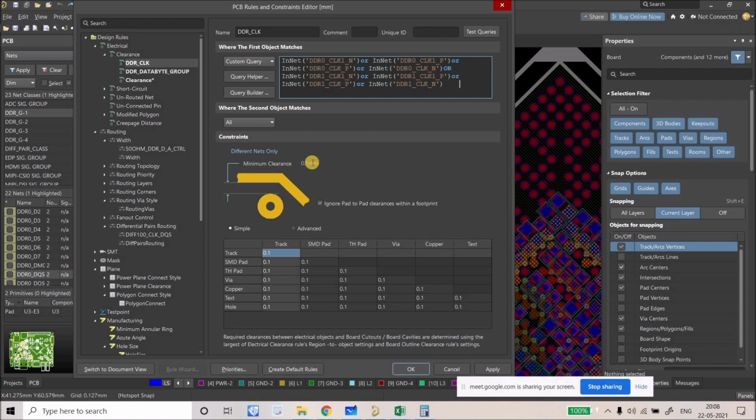We already know that for 100 ohm differential impedance, the width of the track was 0.08 something like that. So if you multiply it by 3, it will be 0.25. Hold on, yeah, 0.25 mm, and enter. Again, we're going to create some exception on this design rule, but for now it is fine. Okay, so this is one thing.